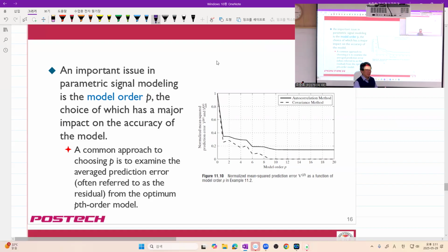One good thing for the all-pole model applied to speech compression was that since linear prediction was not perfect, we didn't have the overfitting problem, but had this beautiful curve like this. You increase the model order, and your error saturates, which means you can just cut at some point of saturation, and that is a very good choice of order.